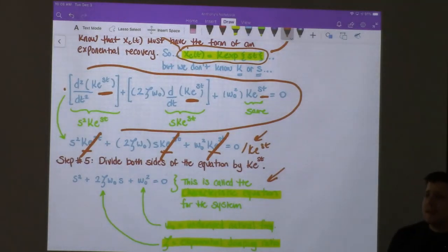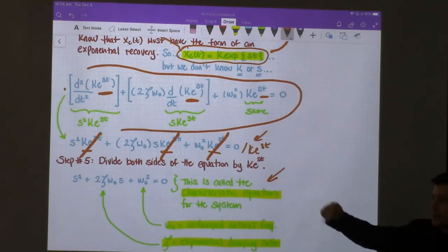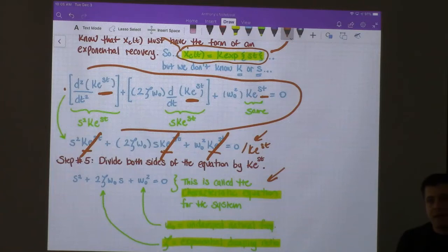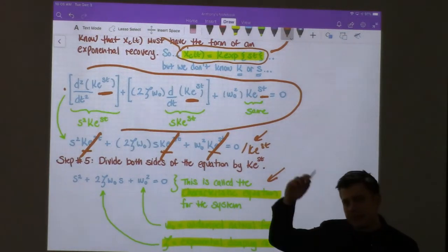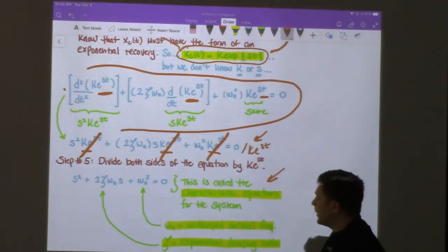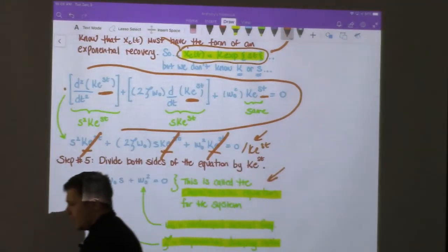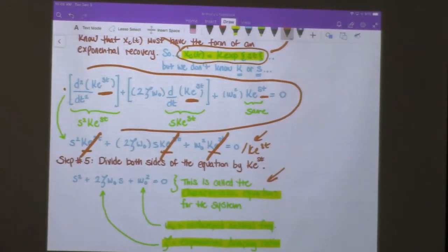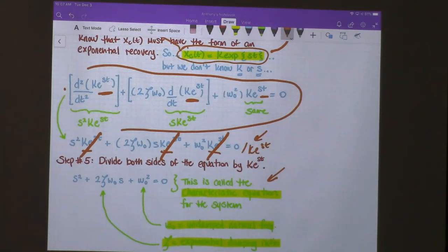And so what we see is that for a second order transient, we no longer always have this exponential response that settles quickly and is always moving in the same direction. Second order transients can oscillate. And then we also have the exponential damping ratio represented by zeta. And so that is the damping term, right? You've all discussed oscillations in some class at some point, and so you're familiar with what damping refers to, right? It's the rate at which the oscillations die.